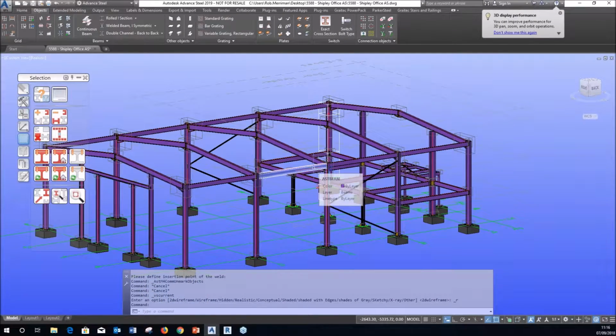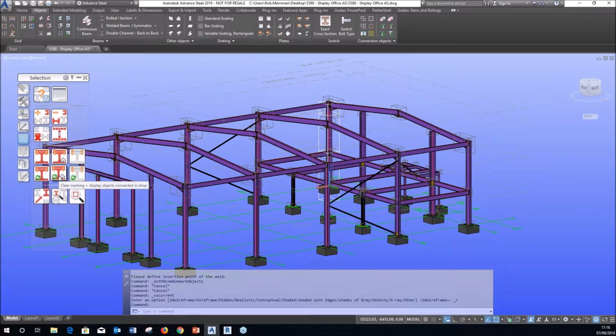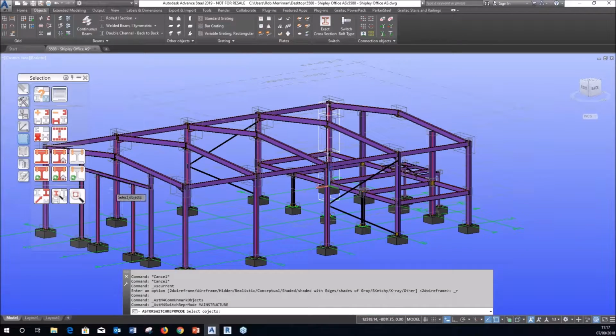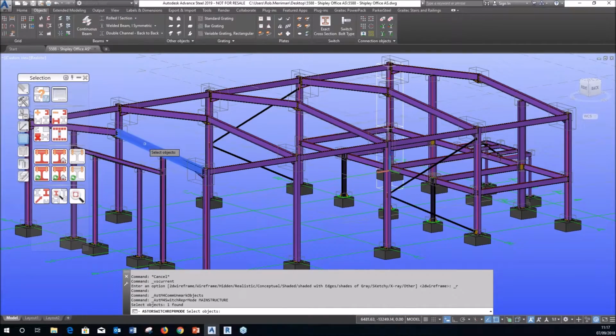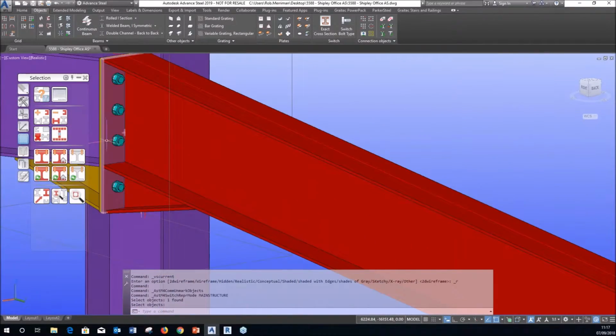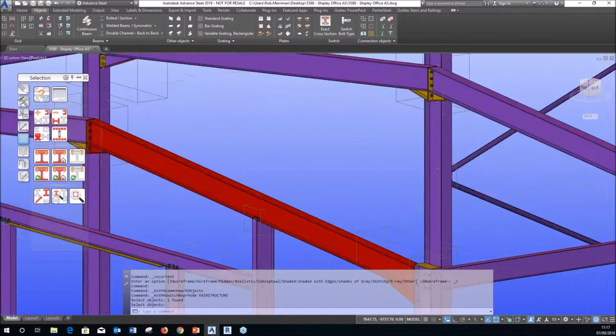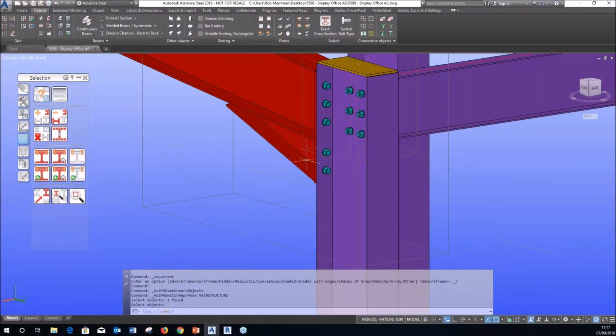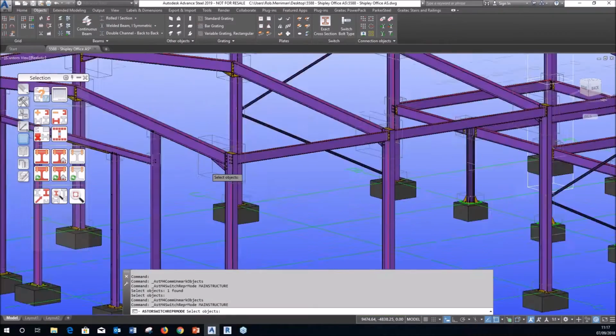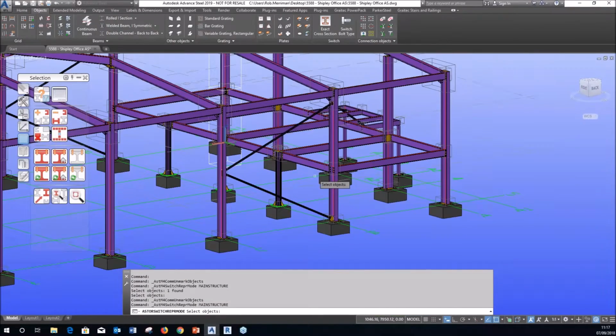When you're manually welding things together in Advanced Steel, we have tools to check what's attached in the workshop. So I can click this button and click on the rafter, and it highlights everything that is attached in the workshop. So I can make sure. Now, like I said, because I've used a haunch joint and an apex joint, it won't mess the welds up.